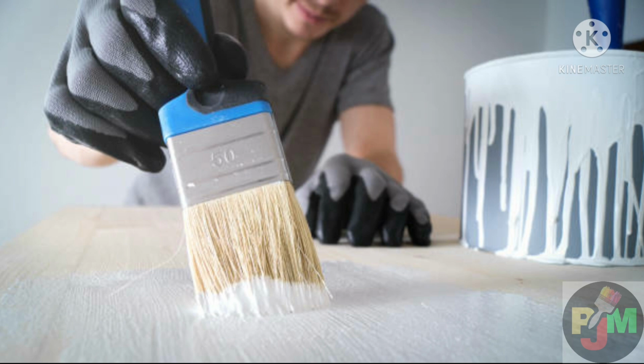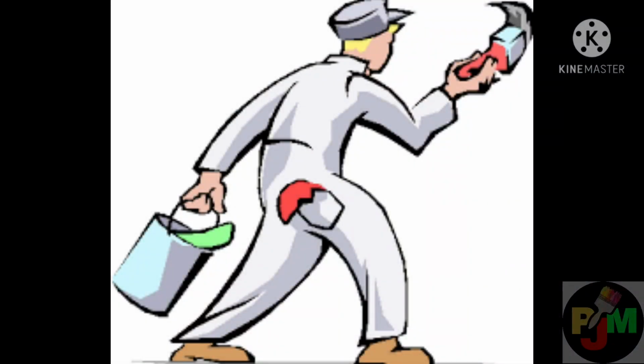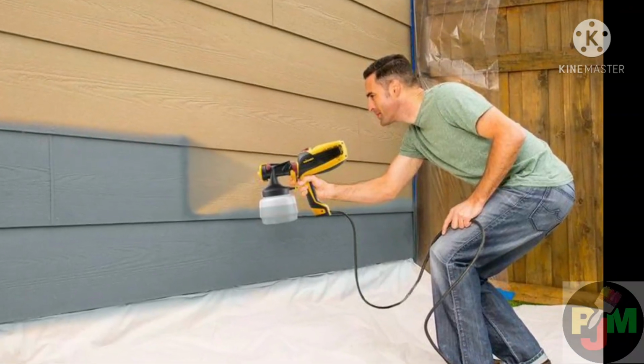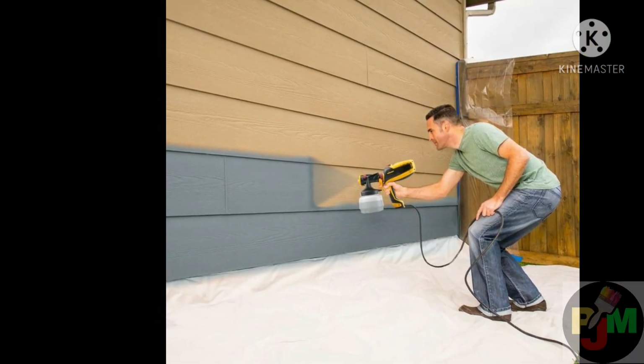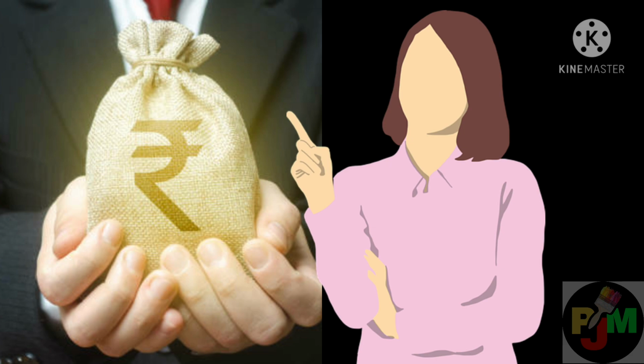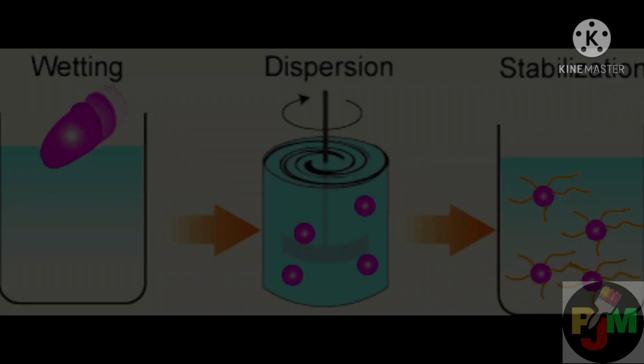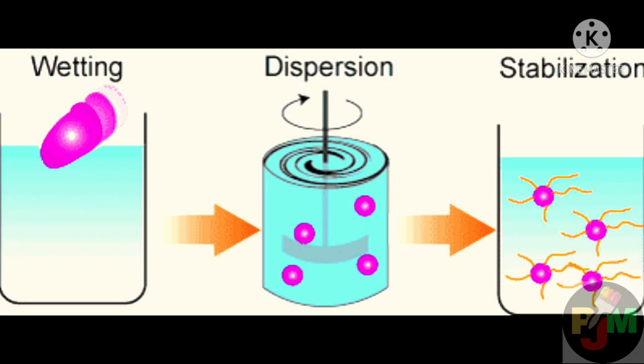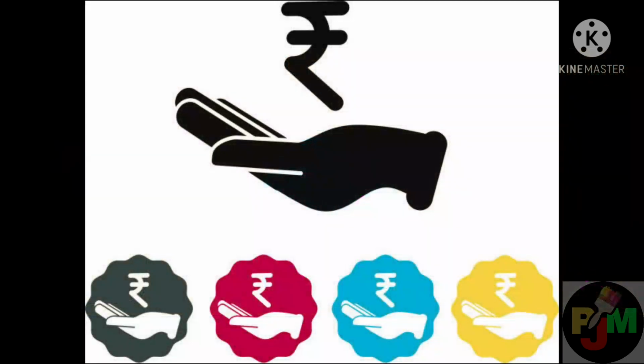During the exposure of the coating, these unsatisfactory properties may lead to inferior opacity and gloss, as well as color differences in the coating film. An additional disadvantage of poor dispersion is that the properties of the expensive pigments are insufficiently used, and thus the raw material cost of the coating is unnecessarily increased. The long dispersion time during the manufacturing process results in high manufacturing cost.